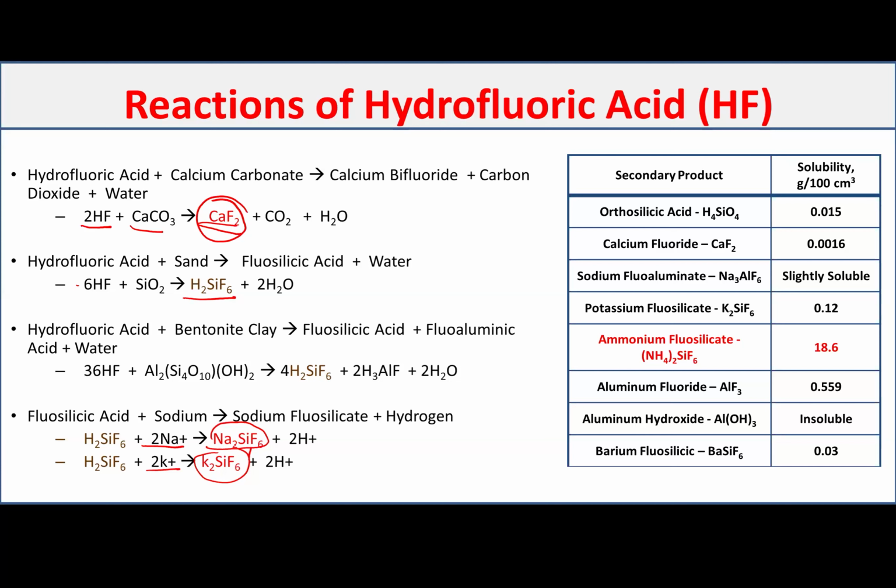Deeper inside the formation, the acid will be mixed with the formation water, and the pH will be increased, and it will precipitate really deeper inside the formation, keeping the near wellbore area pretty clean, and all the damage in the near wellbore area will be dissolved. So what's happening there? You are removing the damage from the near wellbore area, which is the key area for the skin, and having a precipitation, but this precipitation will be happening really away from the wellbore, where the effect will be much less. And that's simply the way the HF acid does it.